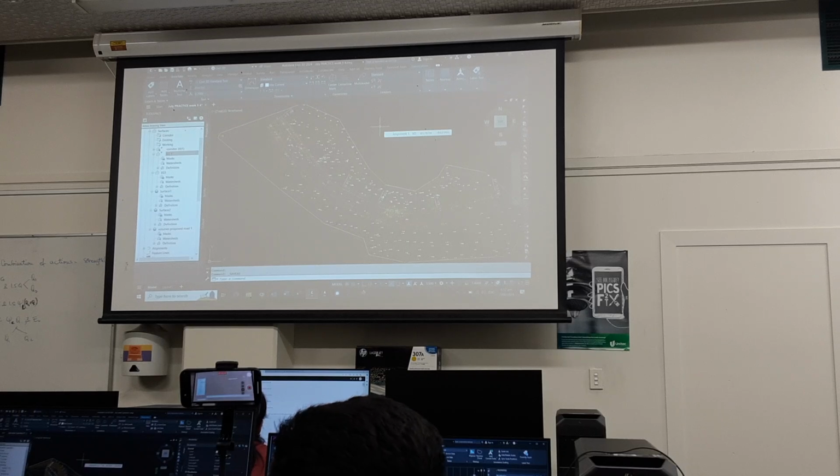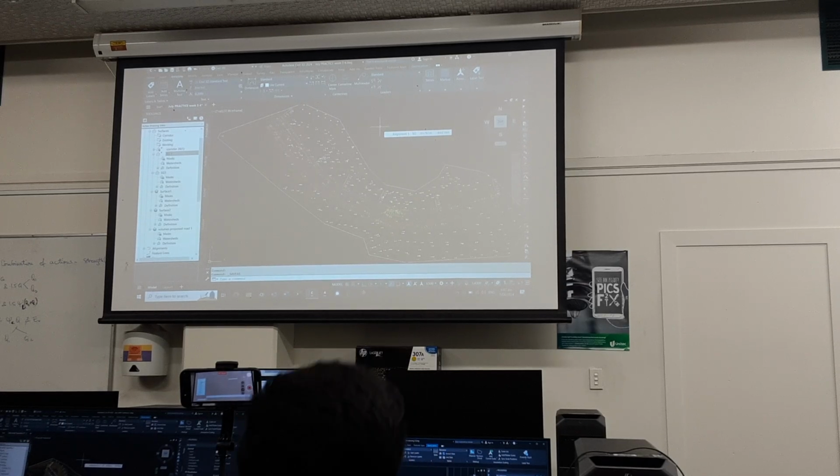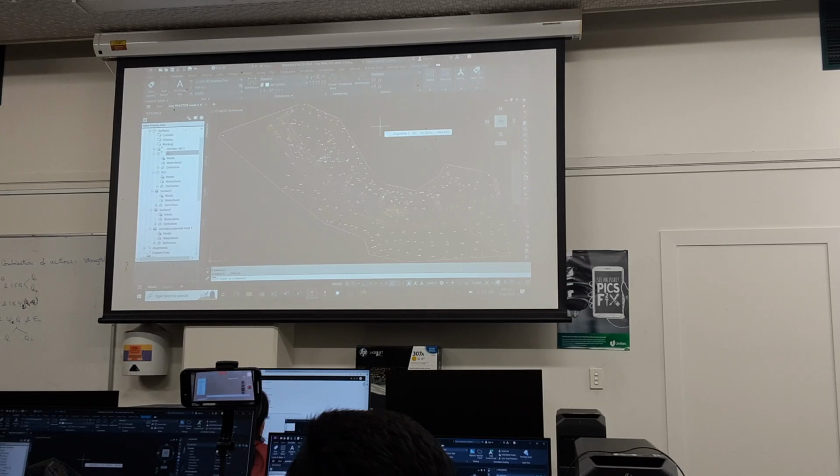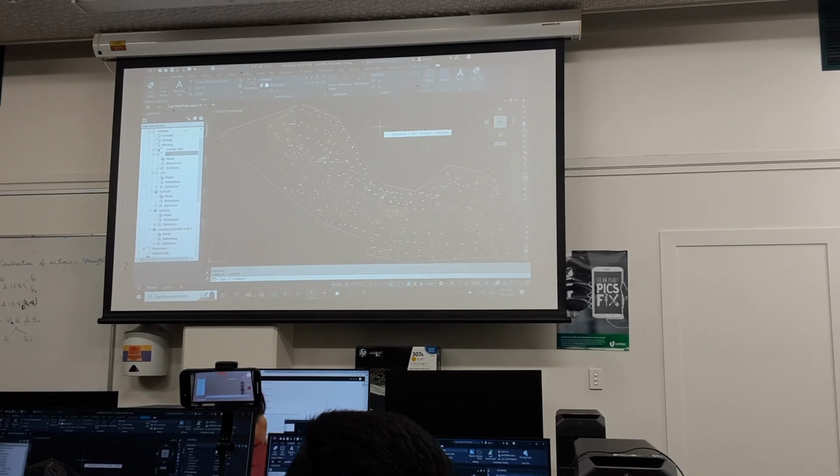I'm going to make you do 10 for this tonight, and 10 for the assignment. But I'm just making you aware that you usually don't have to do 10 for a road. Having said that, if there was a big gully or something on the side that needed to be picked up, you'd be asked to do an extra one at that point. Otherwise the volumes wouldn't be right.